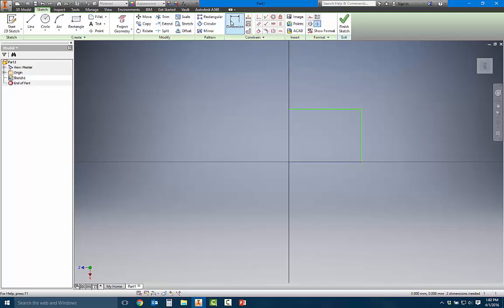So I'm going to click the dimension tool, and I'm going to click on one of these edges. You can see it's a linear dimension. And when I click on that and pull it down, I'm not dragging, I just clicked it following my mouse and pull it down, it gives me a nice little dimension thing, and I can actually set the dimension. So in this case, I'm going to make it a nice even 10, and that actually changed the geometry for this shape. And you can see that it changed from a green line to a purple line. And that means that this design, these lines are constrained, are anchored based on this dimension, right?